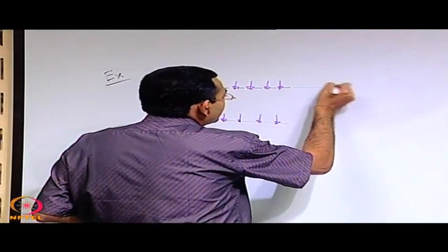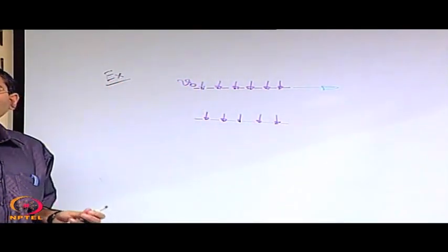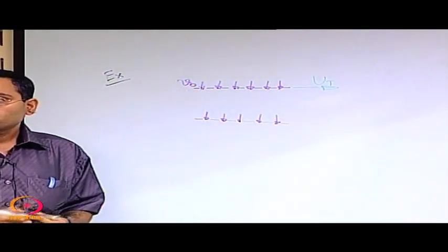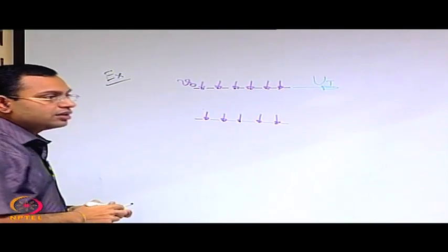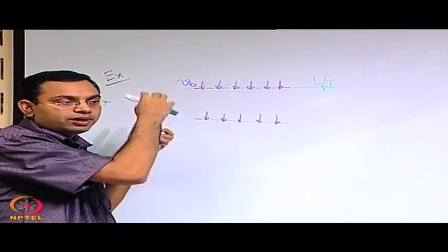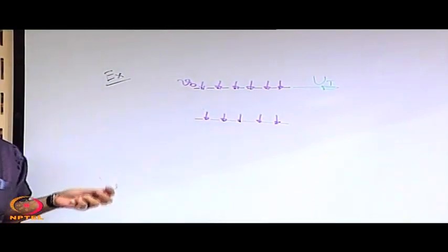The other thing is, let us say that it is basically a Couette flow, so that the top plate is pulled towards the right with a velocity relative to the bottom plate. Let us say that the velocity is U_t. Okay. Let us also assume that it is a fully developed flow. So basically flow between two parallel plates, just like the Couette flow that we discussed while discussing the exact solution of the Navier-Stokes equation.